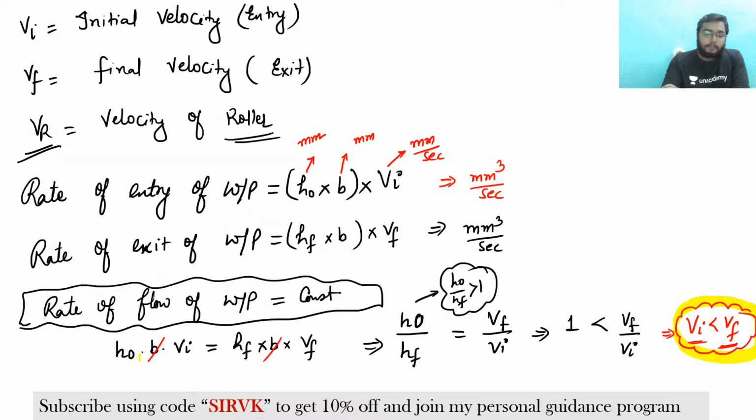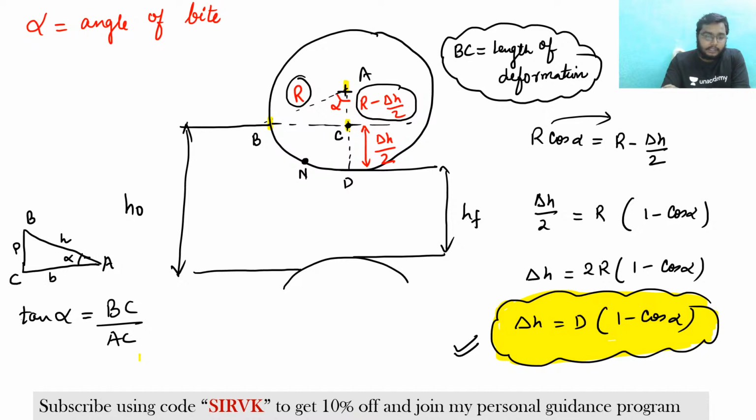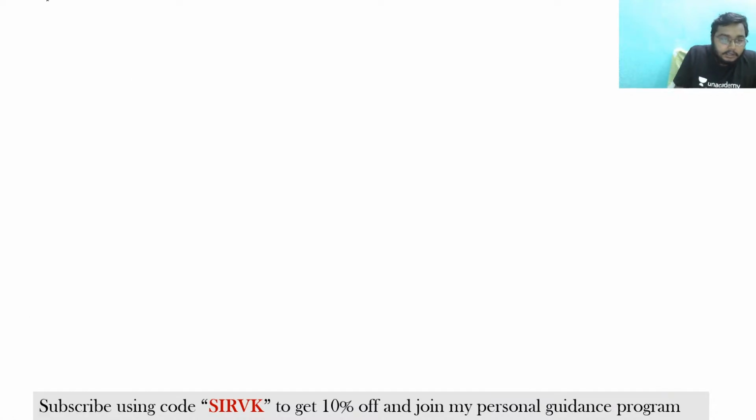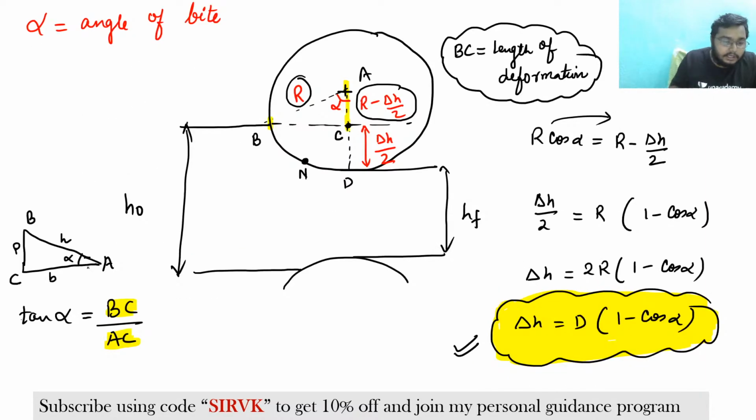Now come back to our topic. We were finding tan alpha, how I can find tan alpha. So tan alpha is BC by AC. Now we know AC, this is the AC, right? Now what is BC? Just now I have calculated, it is root over R delta H. So I can write that tan alpha is BC by AC. Clear?